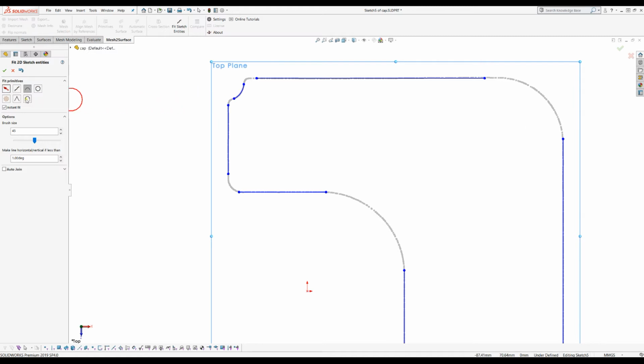Now you know that you can use these modes, and you can always right click and switch from the context menu, but in this case I will not do this. But we introduce a shortcut, which is if you hold the control key and if you move the mouse, you see it becomes blue. The reason for this is so you can just paint, and when you leave, it will actually intersect this. As you can see, this is the way I do this, and I intersect my primitives.